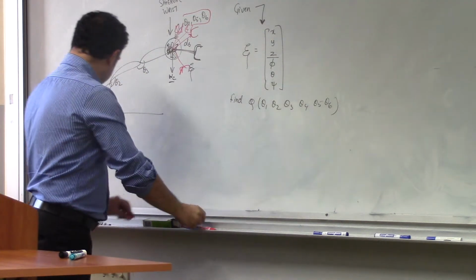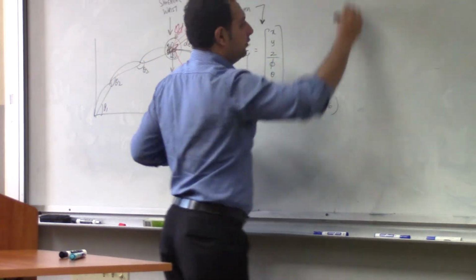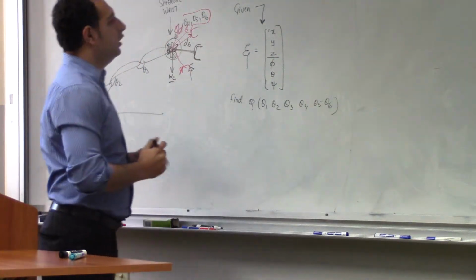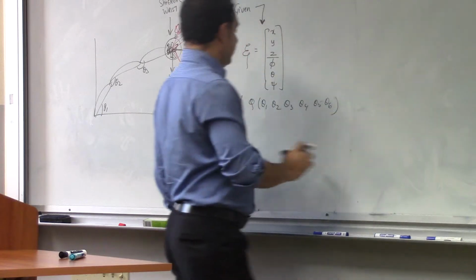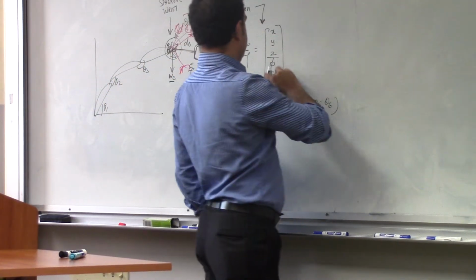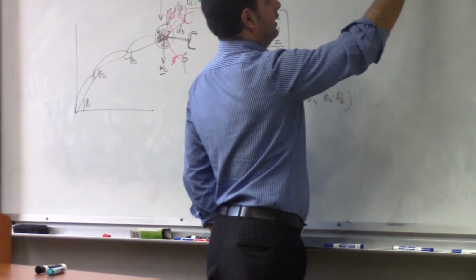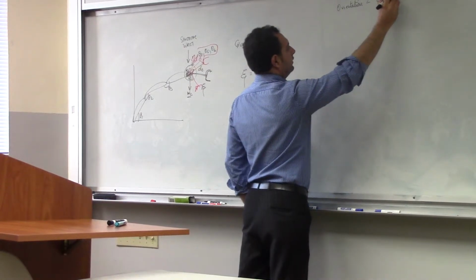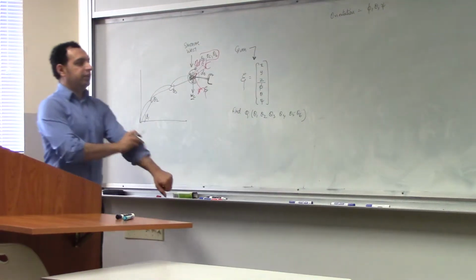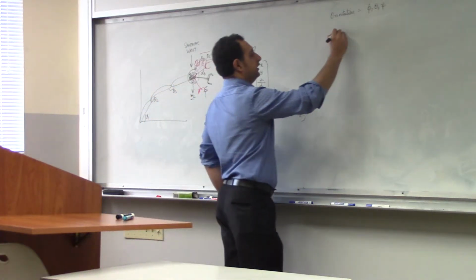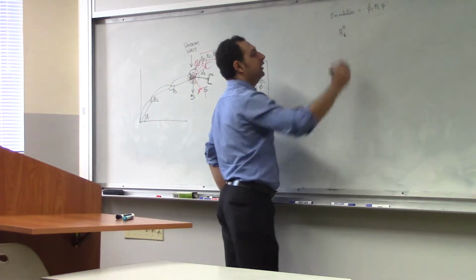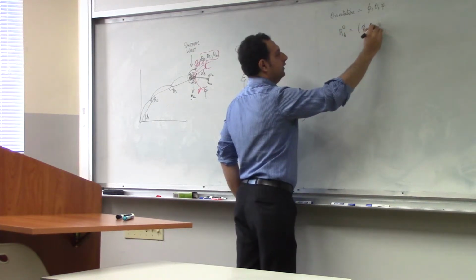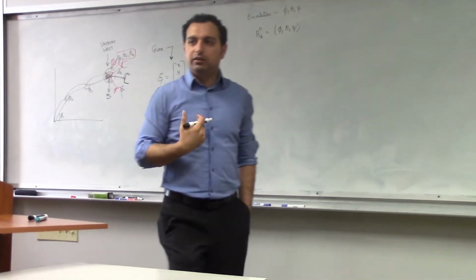So given this, the first step we need to do is find WC. To do that, we'll first start off with defining the orientation. The orientation is given by the angles phi, theta and psi. Okay? So we'll construct an orientation matrix R06, because this is the final orientation, based on the angles phi, theta and psi.